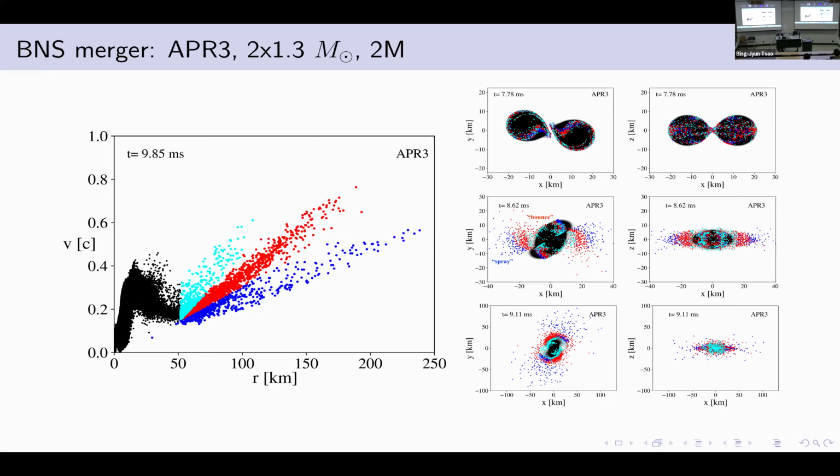In principle, you're correct, but you also have to remember that the kernel goes to zero fairly quickly, so these particles actually contribute a lot less than you might think. The other thing is that if you make it too large, the differences of the metric across the particle are going to be huge.